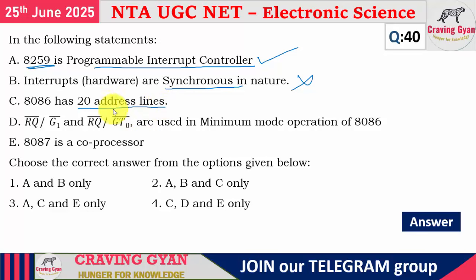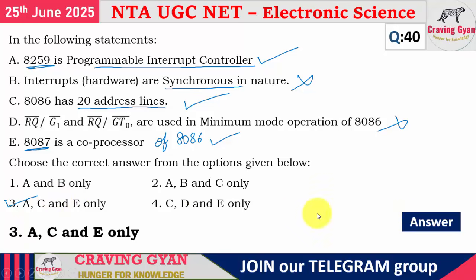So the addressing capability will be 20-bit. Data bus will be 16-bit. Control bus is 16-bit. So option C is also correct. RQ bar slash GT1 bar and RQ bar slash GT0 bar are used in minimum mode of operation. It is wrong. 8087 is a coprocessor of which one? 8086 microprocessor. This statement is also correct. So A, C, E are correct. Nothing but option 3 is going to follow.